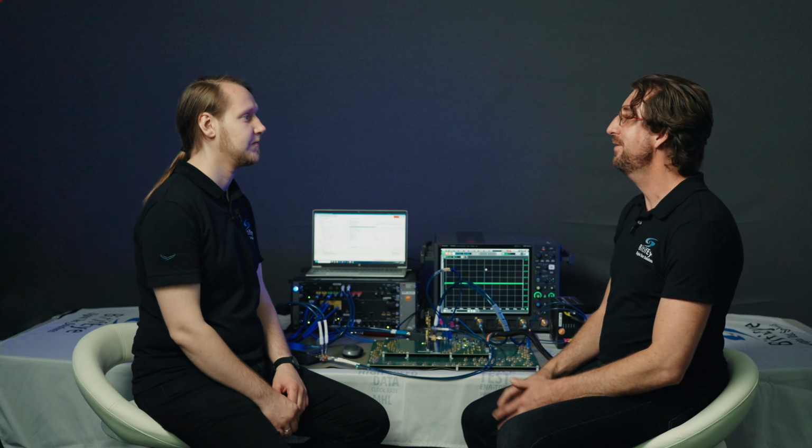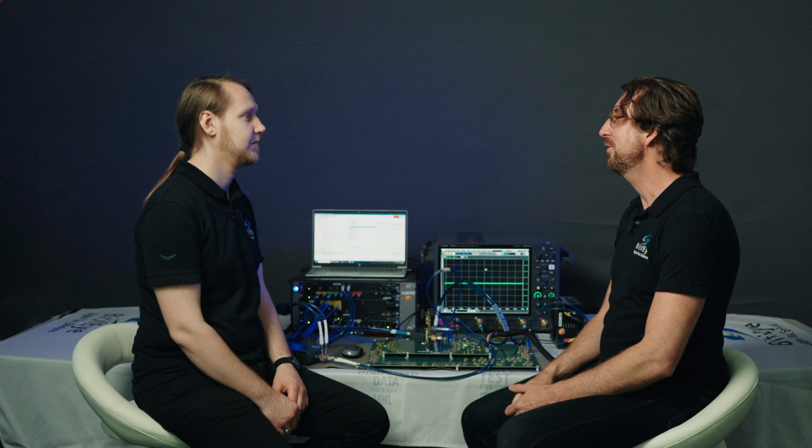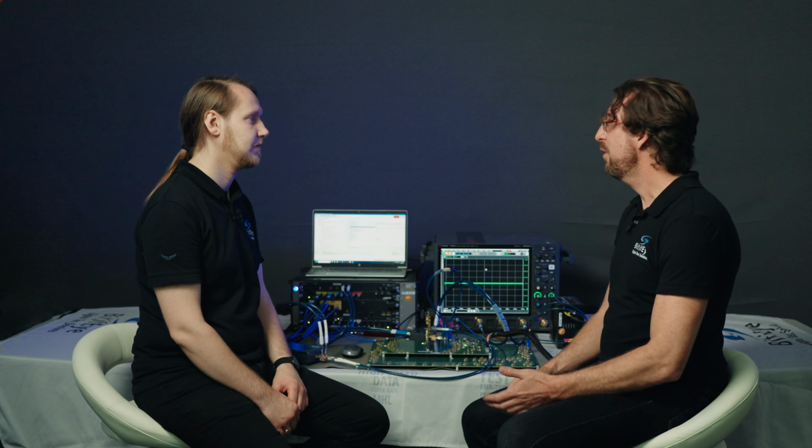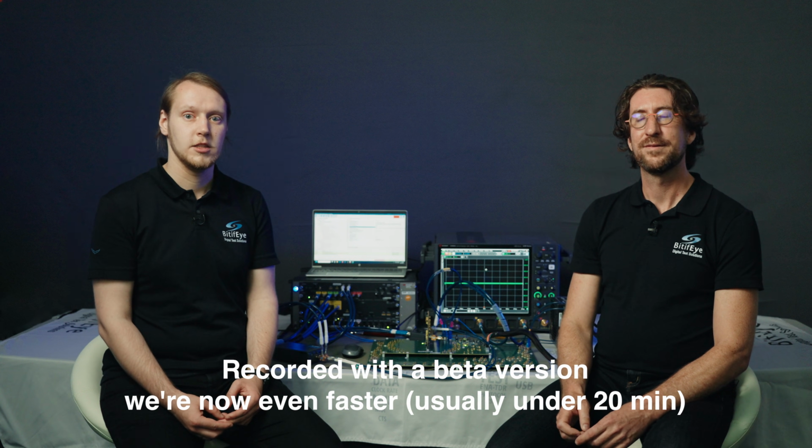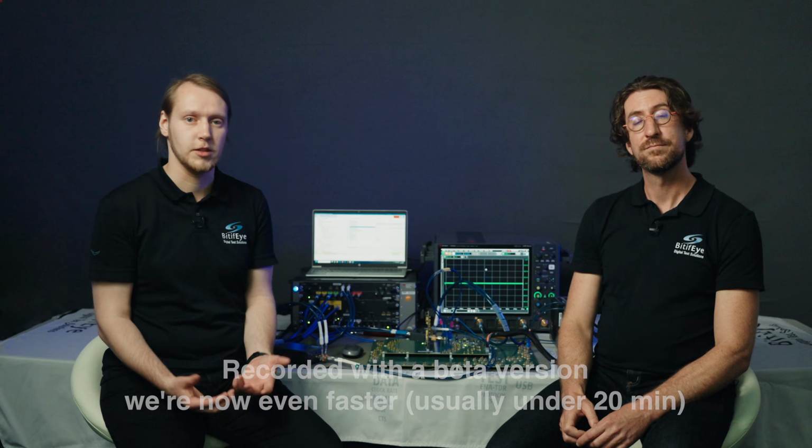Well, thanks for the demo. So if I understand it correctly, that was for a single TXEQ preset. Correct. How long would it take to run for all of the TXEQ presets? And how often would an engineer need to rerun this procedure? Of course, it always depends on how fast the algorithm converges to a good enough solution. However, normally it takes less than 30 minutes, even for a 27.5 dB channel. The optimization finished in less than 40 minutes.